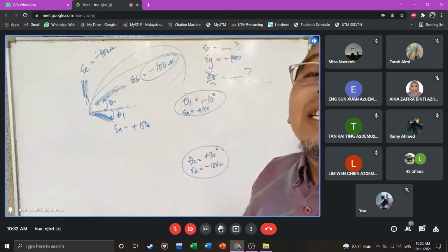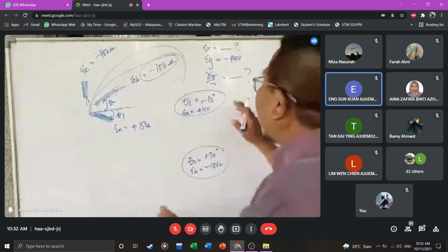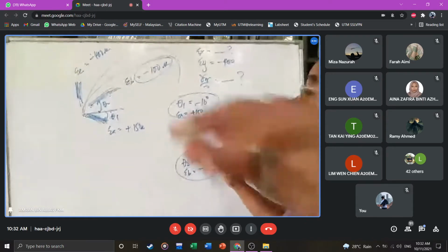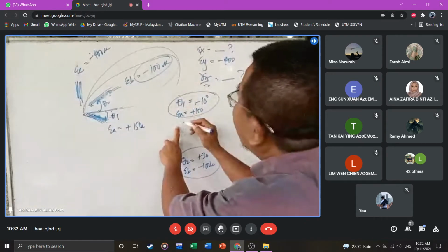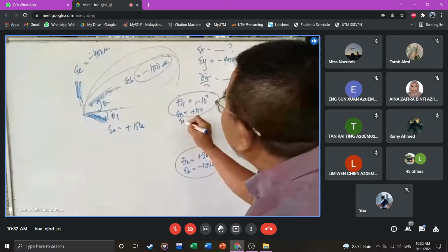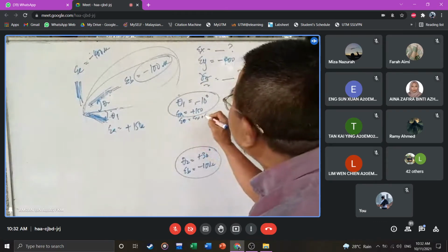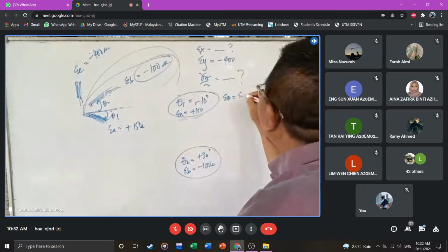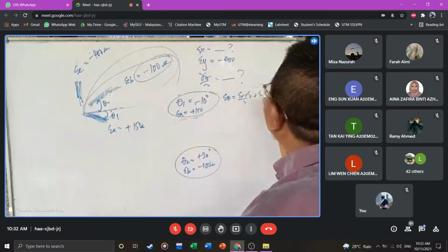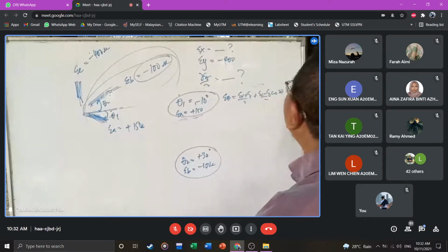Are you with me, guys? Yes. Okay, write that equation. So what do we write there? Exactly, slowly. What is that? That value Ex, remember that? E theta is equal to Ex plus Ey over 2 plus Ex minus Ey over 2 cos 2 theta plus gamma xy over 2 sin 2 theta.